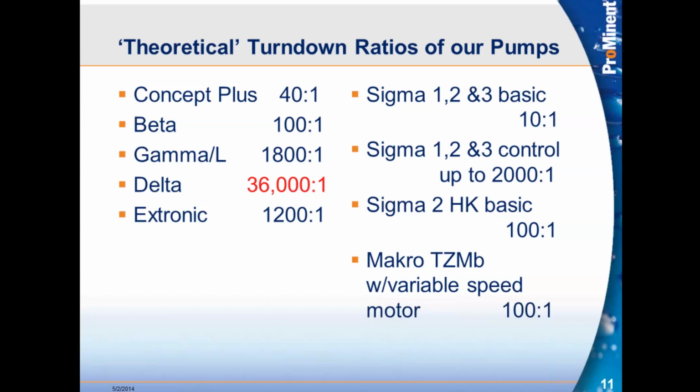We'll come back to the Delta pump. We'll talk about that. The Xtronic pump has stroke length as well as a frequency adjustment on kind of a manual mode of operation. And, be careful on the Xtronic pump. Depending on how you want to control that frequency, you have to order it that way specifically.